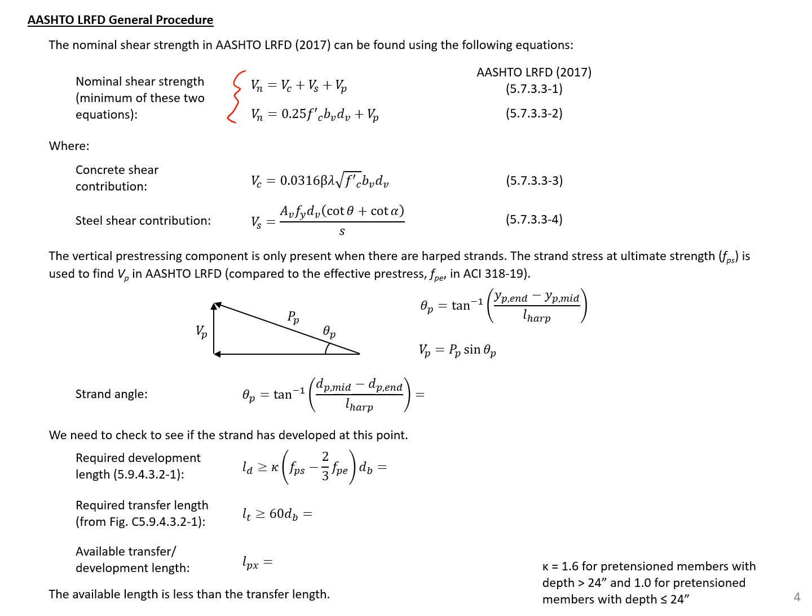So this second equation here ensures that we don't have crushing of our concrete that controls the shear strength. The crushing of the concrete in our truss model can happen at the support, and if this crushing happens, then it doesn't matter if we add more steel, we'll still have failure at this limit.